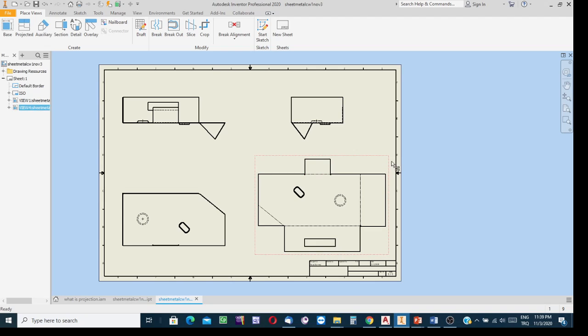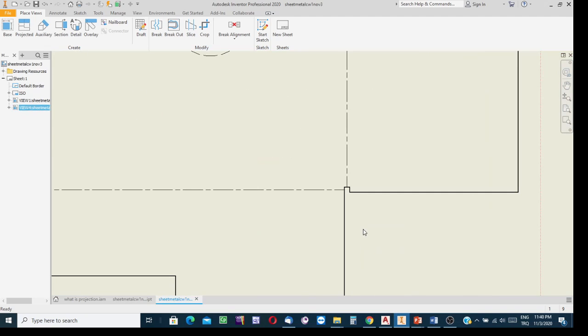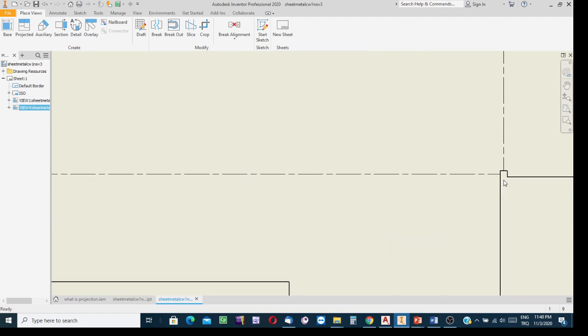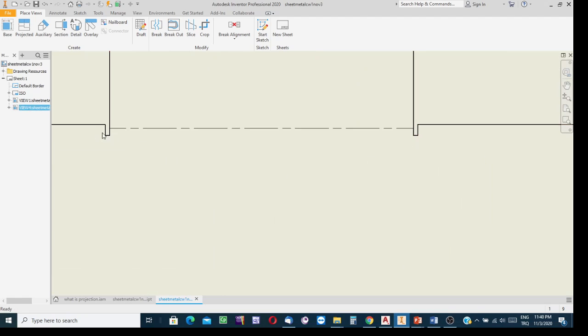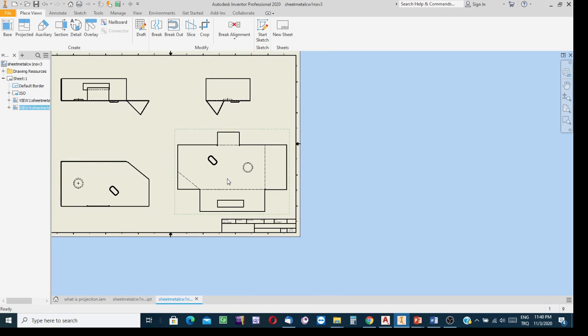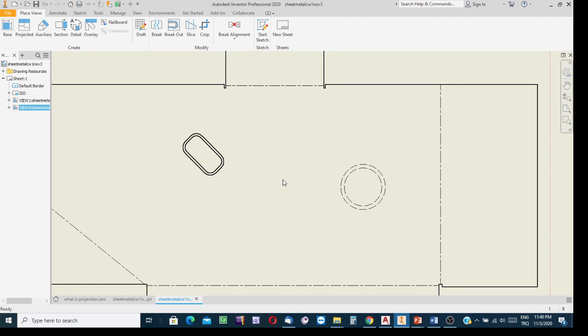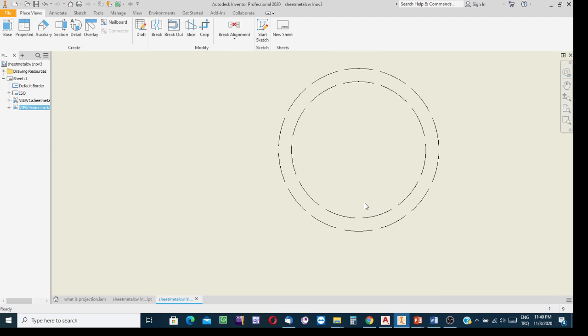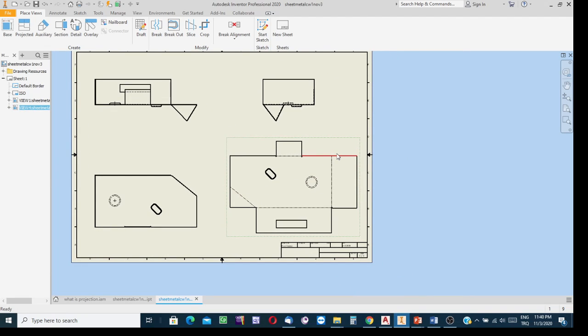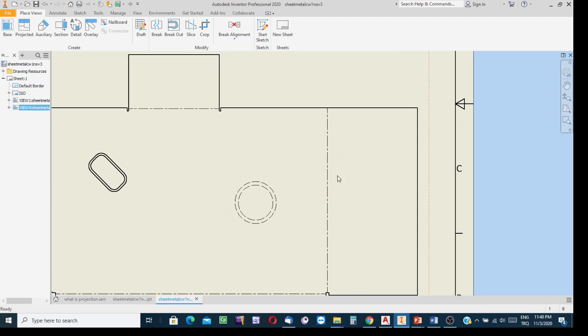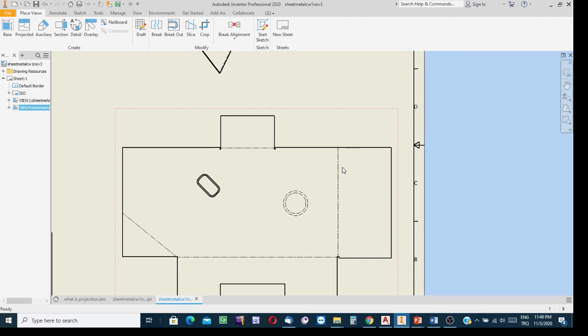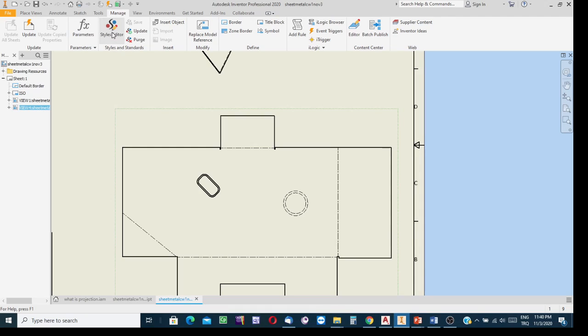And then after having this figure, using special scissors, cut the sheet metal, have such boundaries, and then using the punch process, create this relief. After creating the reliefs, and also why not at this stage or thereafter, after the folding stage, using again dies and special rams, applying the necessary deformation forces, have this emboss, and then fold the sheet metal along these highlighted boundaries. Of course, this boundary is to be coordinated. Dimensions, well, quickly pass through the dimension configuration stage. Styles editor, you know this.